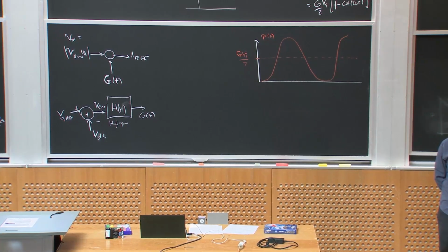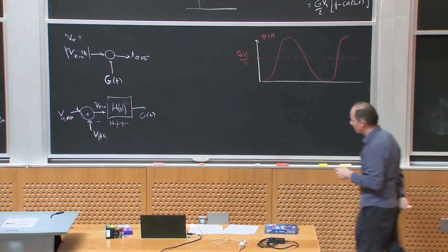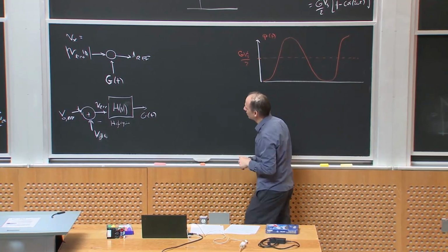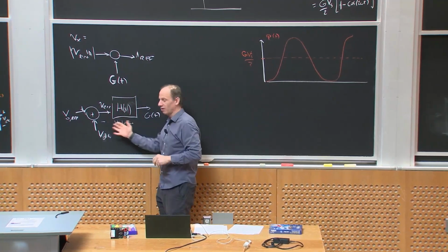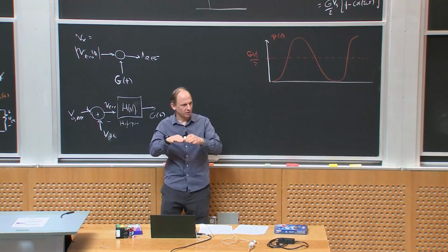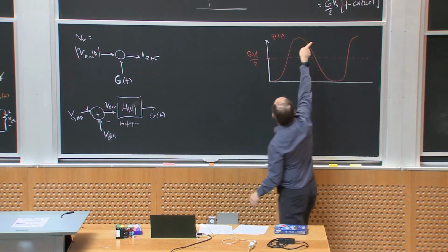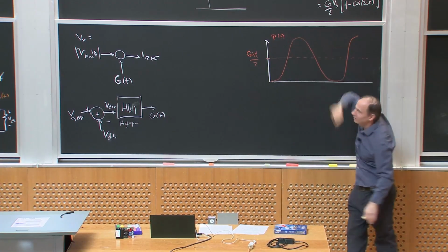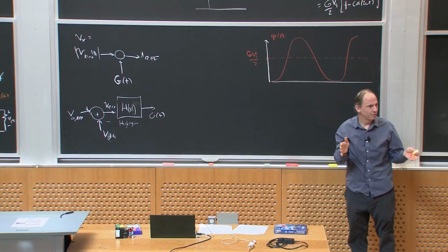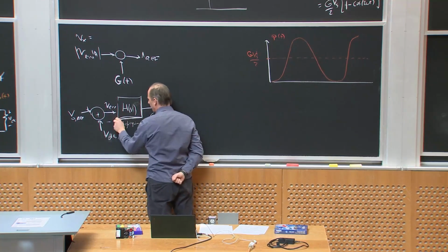So this is a typical kind of controller for a PFC control. Let me explain a couple things here. Keep in mind, what's the bandwidth of this thing, right? Well, G is supposed to be a sort of constant over a cycle so that the AC current that I draw isn't wildly varying over half a line cycle. So the bandwidth of this controller tends to be really slow.